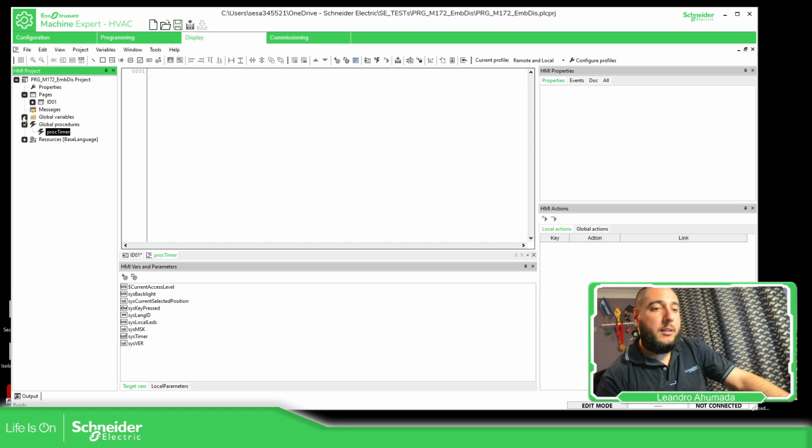They only allow you to use internal values of the system at the HMI. If you want to do that, there is another video where I'm going to talk about the functions we can use, send get param and send set param. I'm going to explain that later. I just want you to understand how we can program this global OnTimer. First we need a procedure, and in that procedure we're going to have our data. Here you can see that this is pure text, so we need to add some logic.